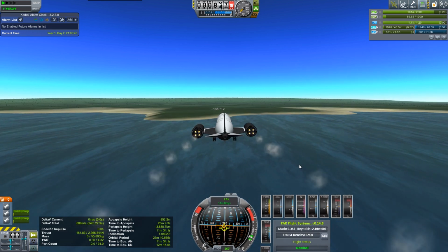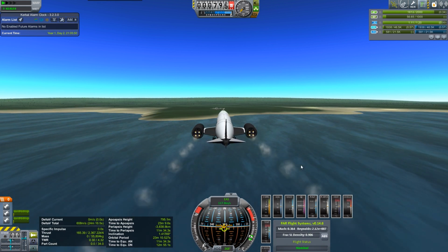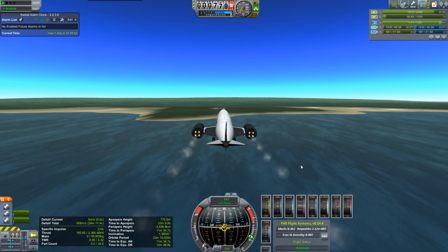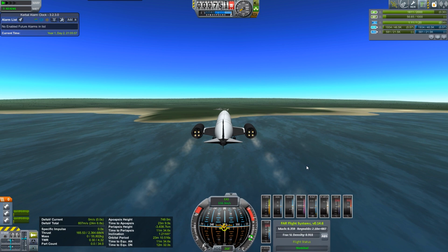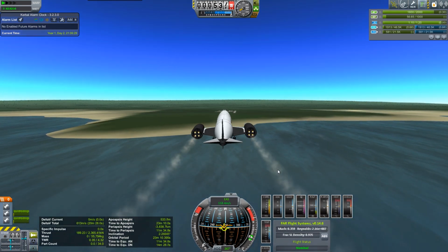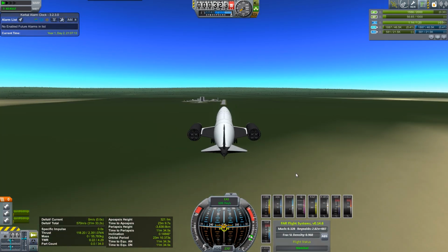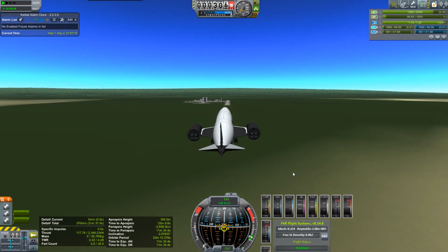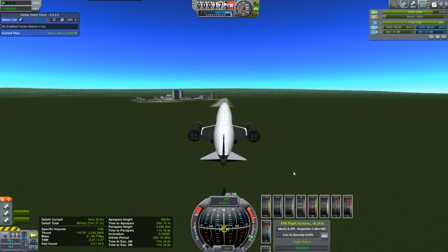Flying this airplane, I found it turns into just constantly managing that pitch trim. That ends up being my primary control, almost. That's what I mess with more than anything else. Yeah, we've got the throttle and the trim setting just about right. Okay, so now we are descending and slowing at the same time. I like it. Okay, try to pitch up more, ease into the flare.